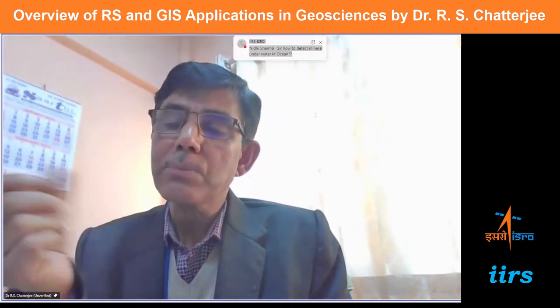First is Surya Kaushik, who has asked how do we merge the two data from radar and optical measuring instruments? You can do that. It is not very difficult, this technique. There are some procedures. You can merge any kind of two data. For that, your spatial resolution should be comparable, similar spatial resolutions. And if you want to replace, like in a multispectral image, you have an FCC, a false color composite image. Then you generate this intensity hue saturation, and the intensity component can be replaced by thermal or microwave, any single band image. That is one way.